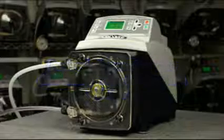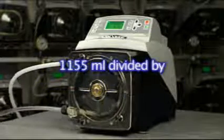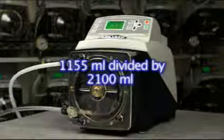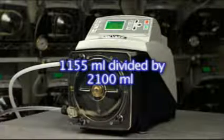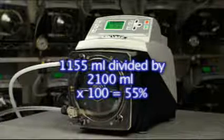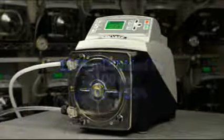For example, if the desired dispensing rate is 1,155 milliliters per minute and the A3's maximum output rate is 2,100 milliliters per minute, then the pump's motor speed during the batch should be set at 55%.